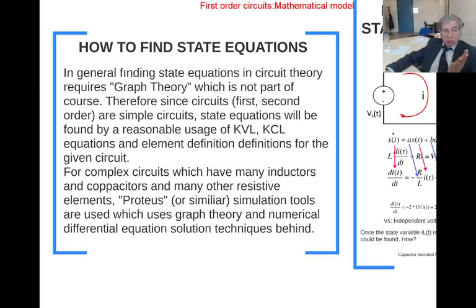How are we going to analyze such a circuit? The number of equations that we have to write is going to increase, and many state variables are going to be seen. So we are going to use the Proteus simulation program for that. This program does it for us by solving the differential equations.